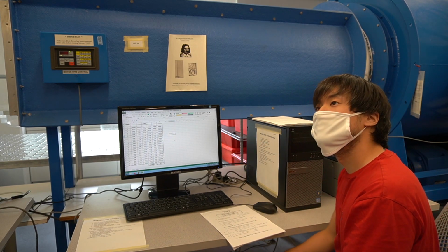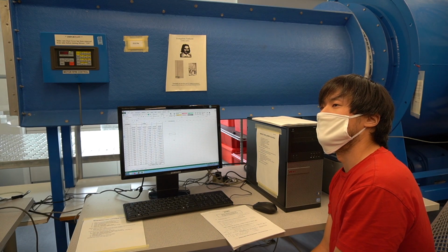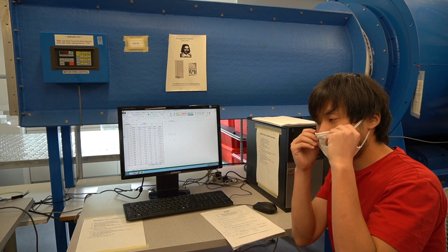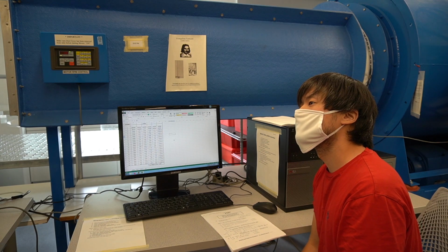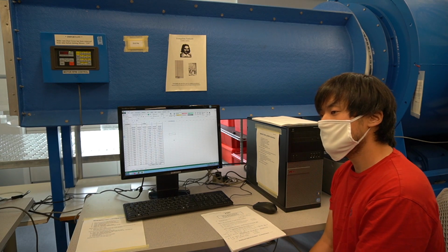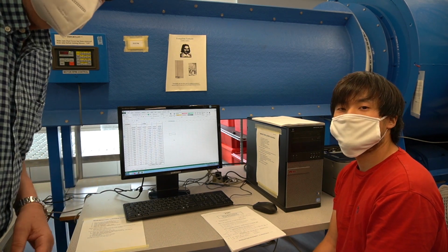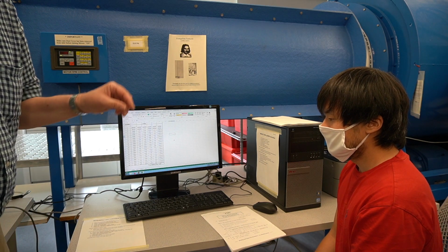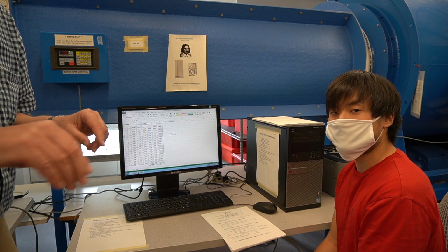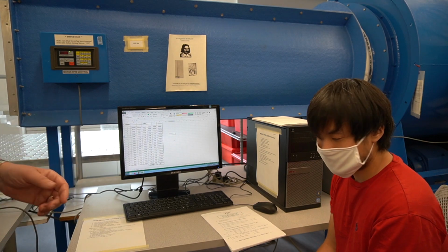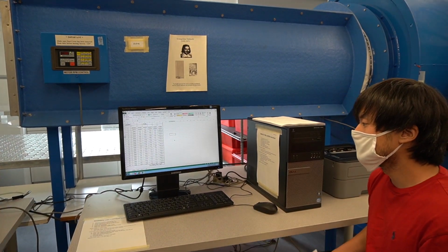We didn't work out the drag coefficient in the bare case, right? We're going to give them the drag data. Did we work it out? It was 2.4 or something? Right, 2.342. So that's a 2.342 drag coefficient for the bare case. So now we put a wake interference plate on the front, roughly 1/10 of the height of the cylinder, and we're going to see what effect that has. We can see what effect that has if we look here. CD is 1.652.